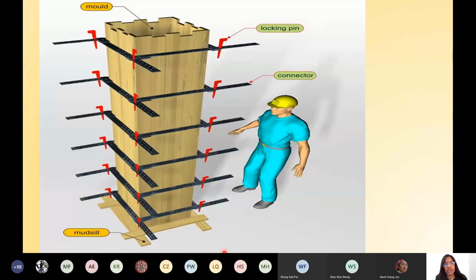We will see how they are done. So this temporary structure, or hollow box, or well, how is it constructed? Here this is for a column. A column box will be constructed like this for constructing a column, and the formwork will have component parts like this. This is the mold. It can also be called a mold, a box, or a container wherein the concrete is poured. Concrete is made or prepared in situ.